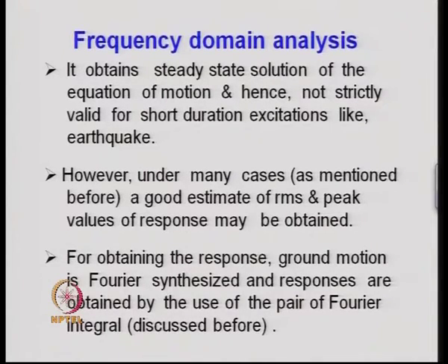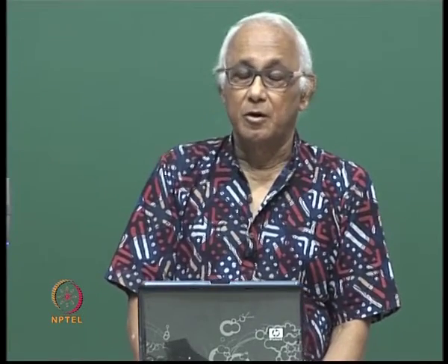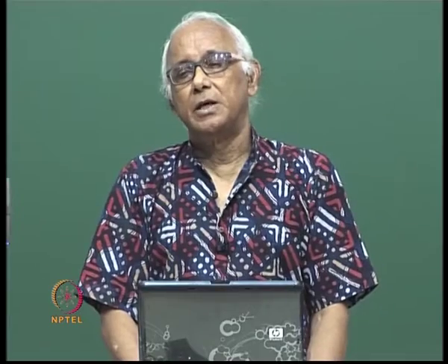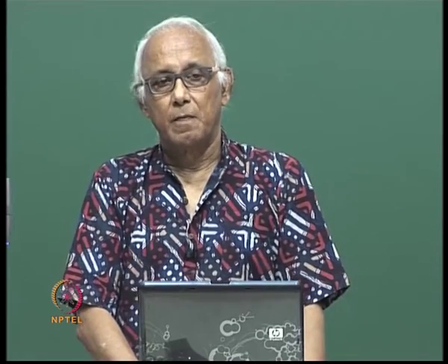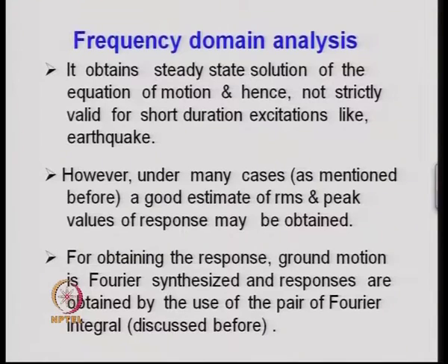The influence of the initial condition, that is the transient part of the solution, there plays an important role, because for the short duration excitation the interval of time t for which the free oscillation takes place, there the free oscillation may not become very small or may not die down. Therefore, the steady state solution using frequency domain analysis may not be applicable for short duration earthquake.